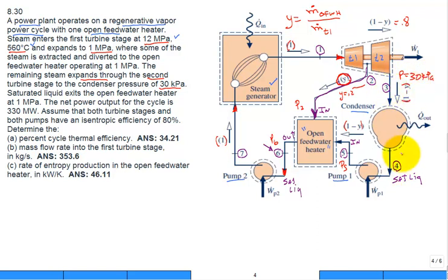Well, you go through the condenser. What's the pressure at state 4? Well, our standard assumption about a condenser is it doesn't change the pressure. It's also 30 kilopascal. And then from 4 to 5, there's that pressure boost. That's the purpose of the pump.